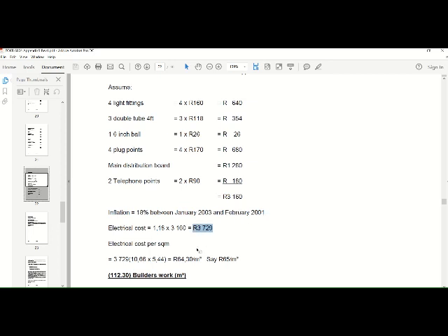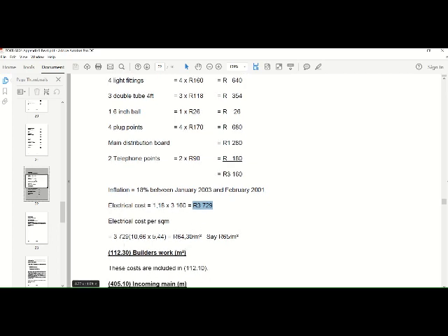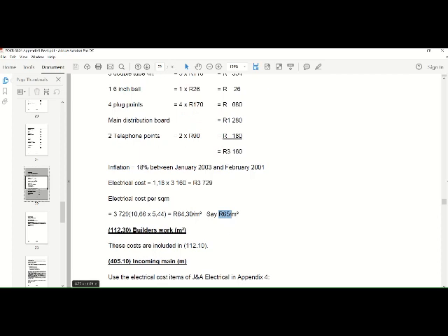So that is applicable if, for instance, you've got a bill of quantities that was done in 2016 and you want to escalate it to 2020 to get to a rate. Okay, so you would see what they've done here is they've taken this rate that they have here, they actually multiplied it with the square meterage to get to a rate of 65 Rand per square meter. Okay, and then you would see here it was included in the rate that they actually built up here.